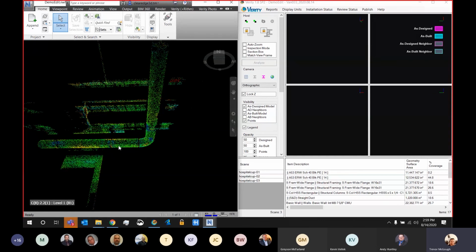The reason for that one is because this allows us to take the information out, again, especially this information right here that shows those subtle as-built conditions. Pop it out as a point cloud. That point cloud will be in the same coordinate system as the model geometry. I can bring that back into Navisworks, or I can take it a step further and bring it back into, say, for example, Revit, overlay this heat map on my Revit model or even my CAD geometry, and then show, hey, this is what needs to be updated or fixed, or this is what we can use to fix and tweak the master model in Revit.